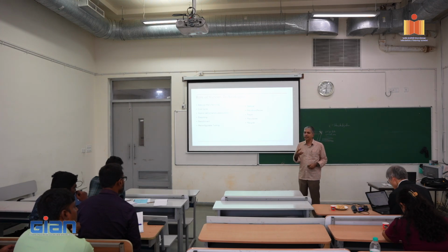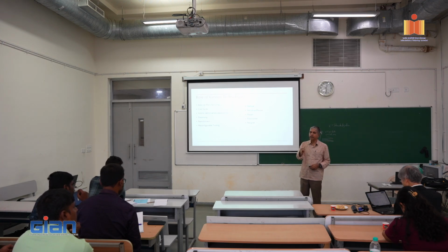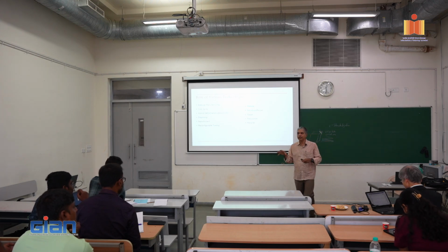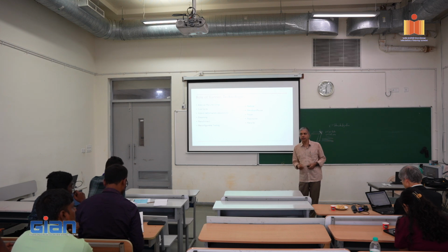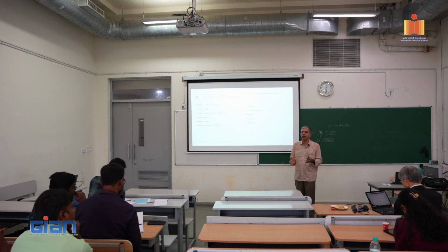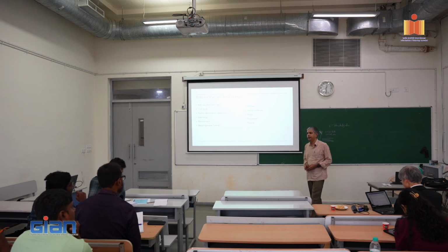Your laser power then increases or decreases, ensuring that the deposited molten pool is at the same consistent temperature you have set. That way, ensuring material homogeneity becomes easier. It is possible.